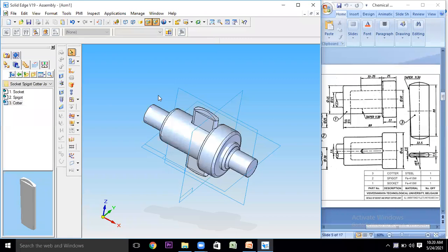we have to go for the section. So to create that section, which portion has to be kept and which portion has to be removed, to show that we have to have two sections. Now in the earlier quarter joint we had only one section because it was symmetric in nature, and if you cut one part another part will be easily visible. But here we have to have two sections just because this quarter is also there.